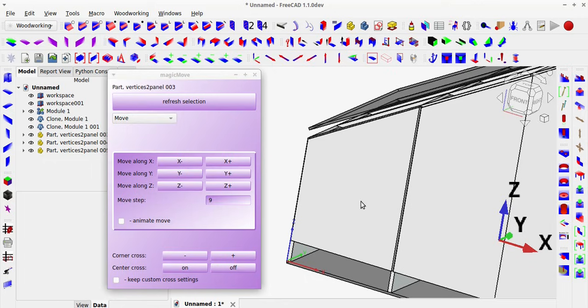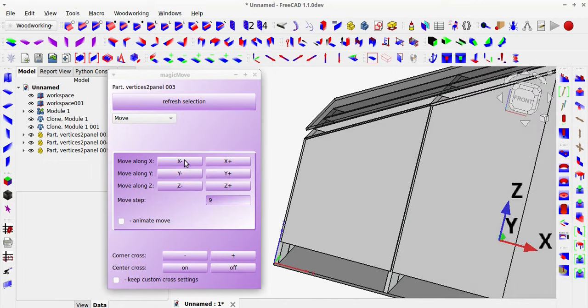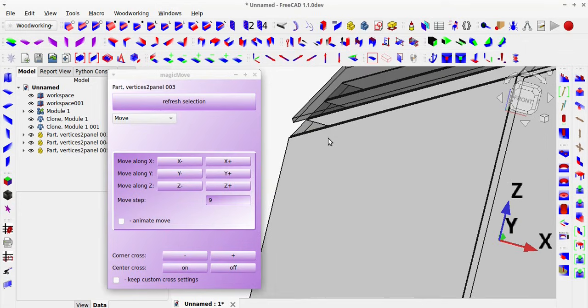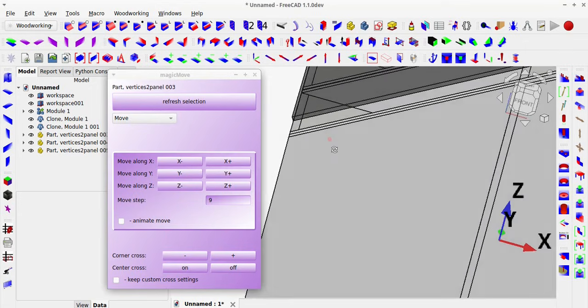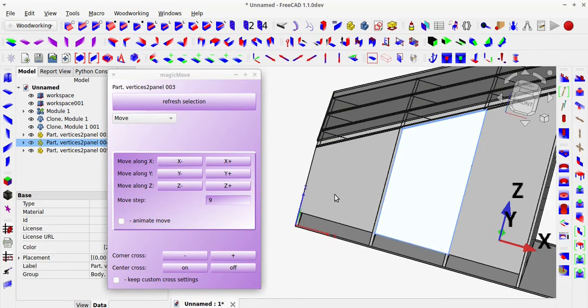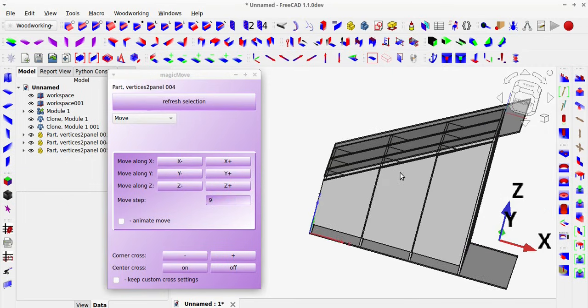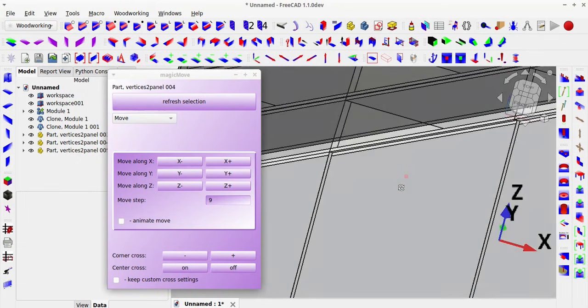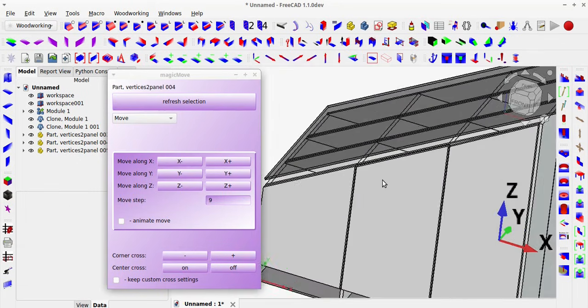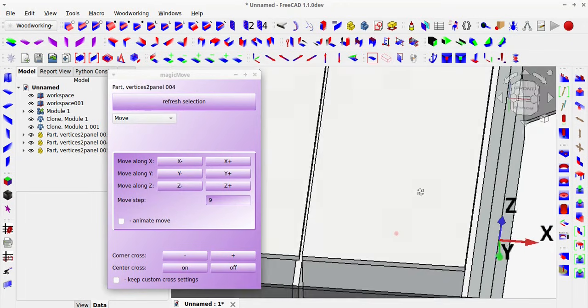Much depends on the availability of hinges and the spacing tested in practice. In Poland, after tightening all the screws, the typical domino hinges center themselves in the center of the furniture gap for the front, leaving a 9 mm overlap on both sides. These are the cheapest hinges in DIY stores, but they have a soft close mechanism and have been in my kitchen for 2 years without any problems.